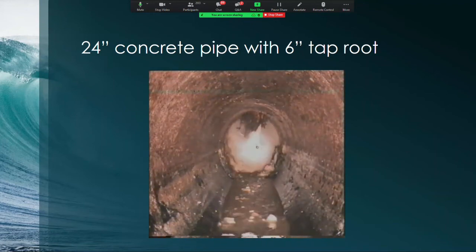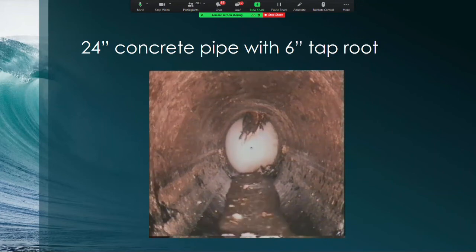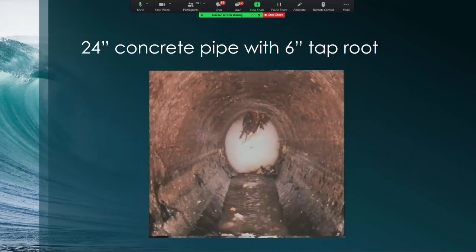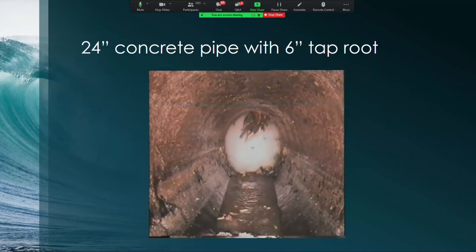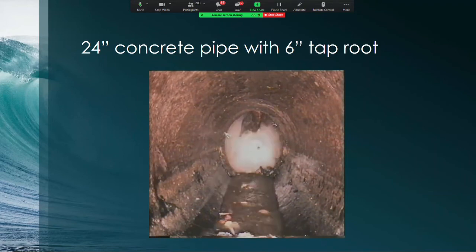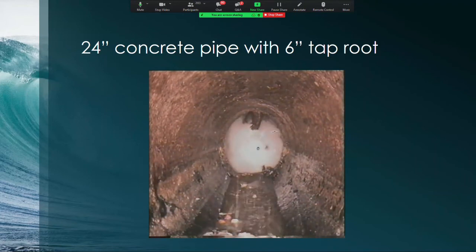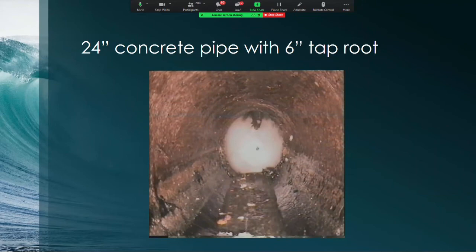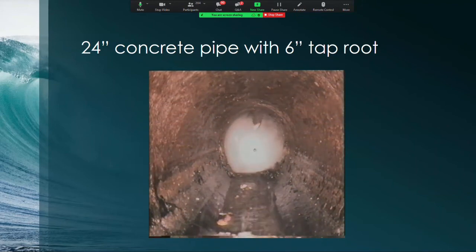See this thing go? People get into problems with chain cutters because they undersize them. And this is a 24-inch pipe. If this is configured correctly, it's going to be 23 inches and change. And it's got very little wiggle room, which means that the tool can't get turned around. If I ran this as a 16 or an 18-inch in this 24-inch pipe, it'll be all over the pipe, bouncing around inside, damage the pipe, and break the tool.